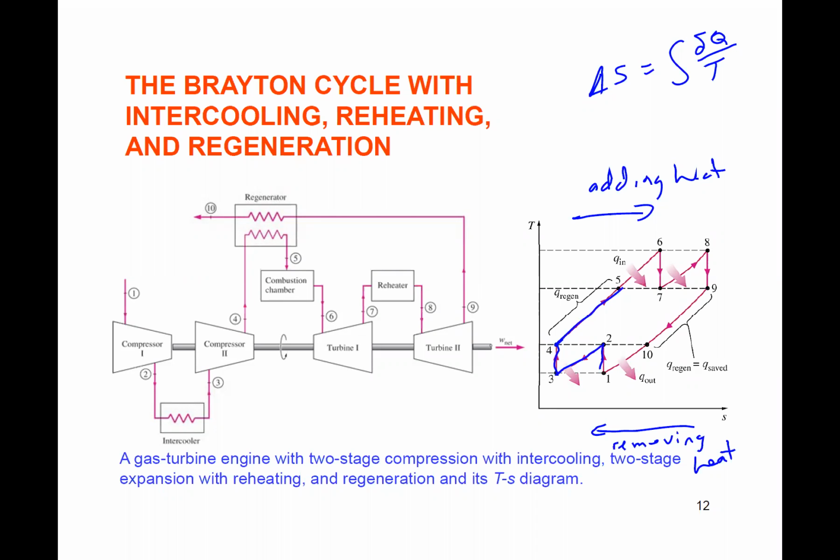It's constant pressure, and then we have our combustion chamber, keep going. Isentropic through the turbine, and we have a reheater. So at constant pressure, we're adding heat. Isentropic expansion, and then we're moving thermal energy 4 to 5, and then we have our heat rejection over here. Okay, so right to left. You just got to step through each component.